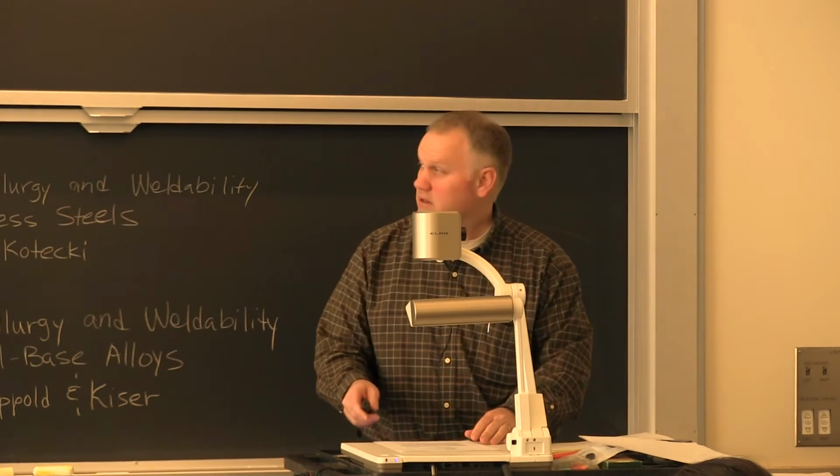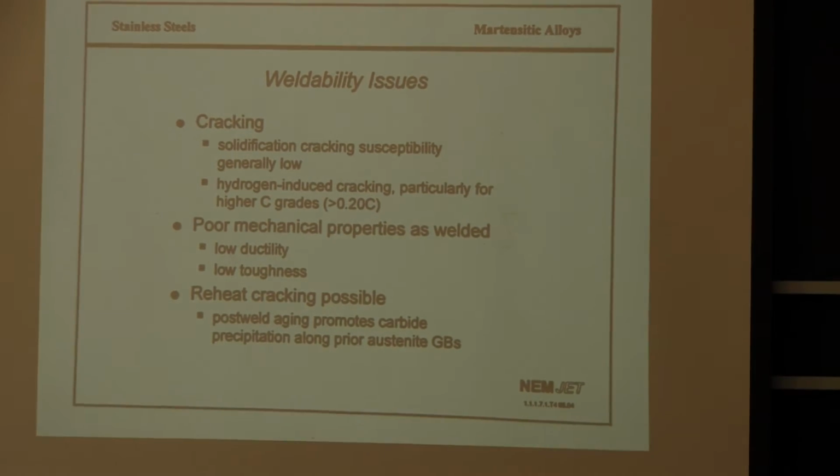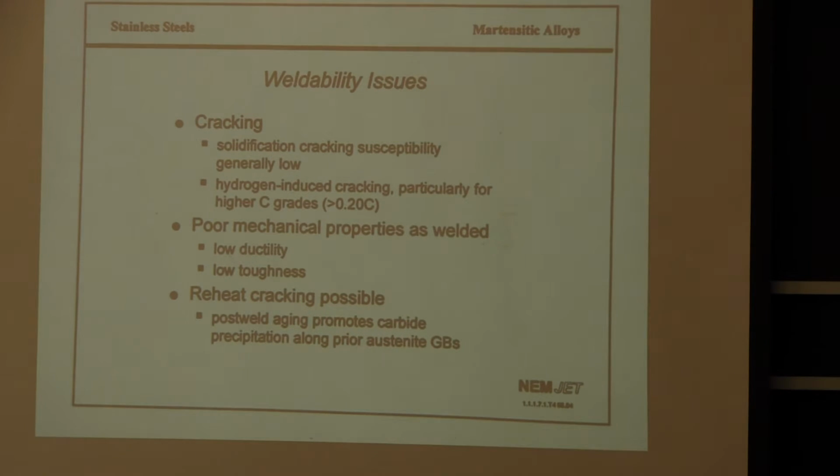So just continuing along the lines of weldability of the martensitic alloys, as far as cracking goes, solidification cracking susceptibility is generally low in these alloys, but the main concern is hydrogen-induced cracking, particularly for the higher carbon grades.